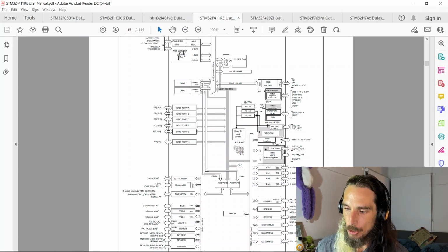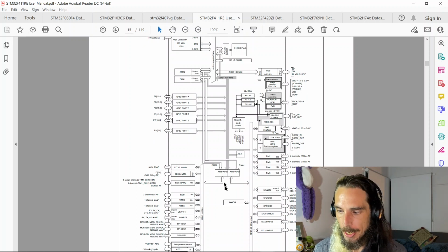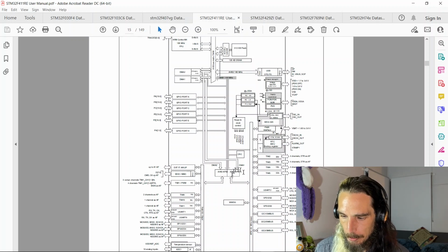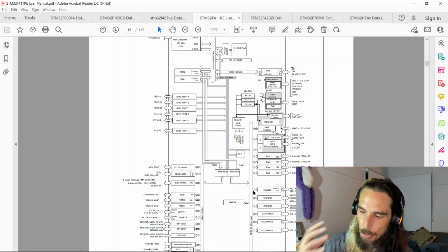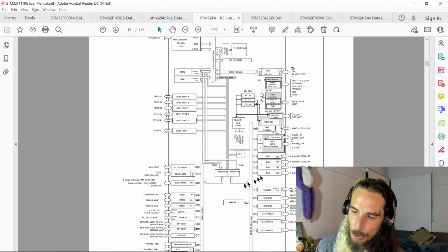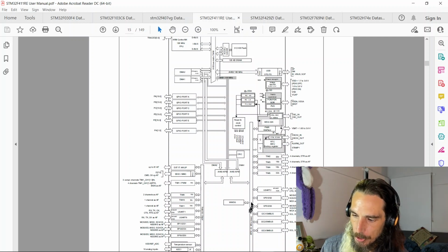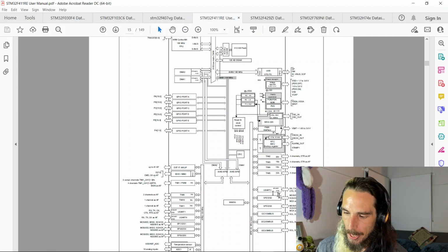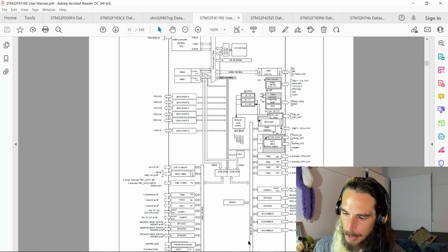For example, if we jump back to our F411 diagram, say we have the CPU needing to continuously access USART2, it's having to go via the bus matrix and then AHB via the bridge to APB1. If it's regularly accessing that and streaming a decent amount of data, and then we go to get, say, DMA1 to start sending or receiving data through one of the SPIs on that same bus, then that's going to mean increased traffic on APB1.